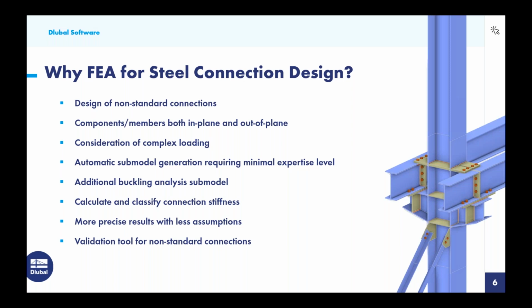We also now have the ability to calculate and classify the connection stiffness. Now, where this is a benefit is that we can then modify our global model to account for the true connection stiffness properties, which are inevitably going to affect the internal forces with the analysis.